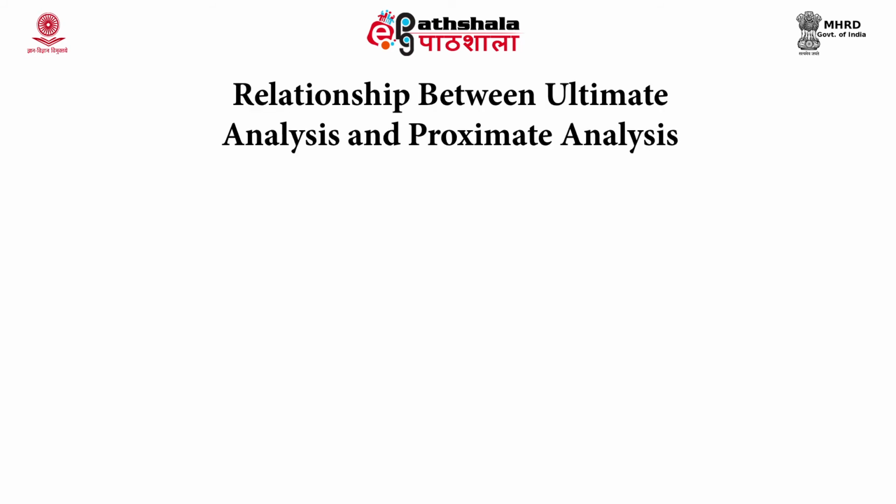Now, what is the relationship between the ultimate analysis and proximate analysis? The percentage carbon is equal to 0.97 C plus 0.7 multiplied by (Vm minus 0.1 A) minus M multiplied by (0.6 minus 0.01 M). Here C is the percentage of fixed carbon, A is the percentage of ash, Vm is the volatile matter percentage, M is the moisture percentage.